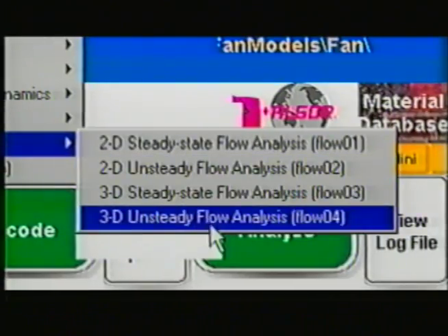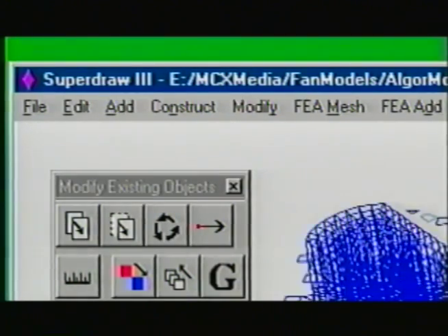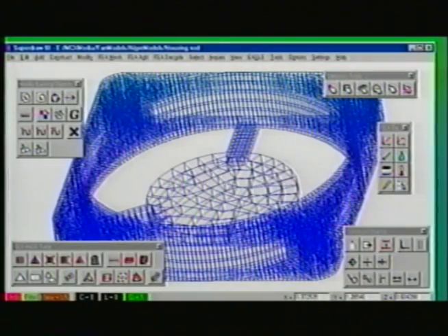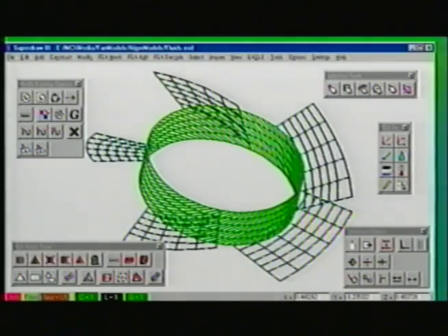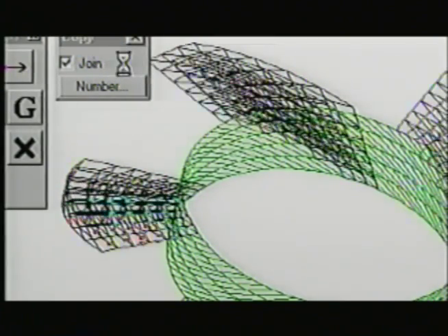The finite element model of the blade and housing was made in ALGOR SuperDraw. The real fan was photographed with a digital camera to produce a bitmap. The engineer used a tracing function in SuperDraw to construct the blade geometry of the model. SuperDraw needs only a few mouse clicks to create the mesh around the blades. Next, a surface mesh of the remaining volume was automatically generated and fitted to the previously created mesh. ALGOR Hexagon made the 8-node brick mesh connecting the blades and support.